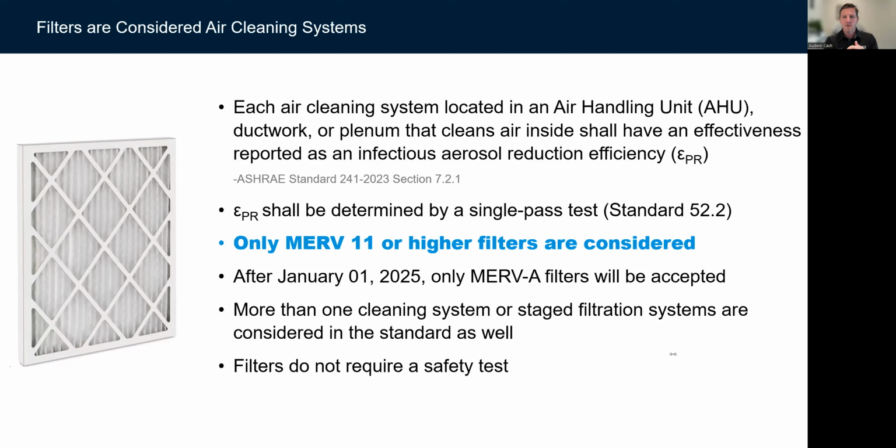So this is the removal value just on the mechanical properties, no electrostatics. That is what's required starting 2025. Why is that interesting? Because we know MERV 11 filters today, when they go through an A rating, will actually have a lower performance. But a MERV 11A will have MERV 11 performance even after electrostatics disappear, okay? Hopefully that's helpful.